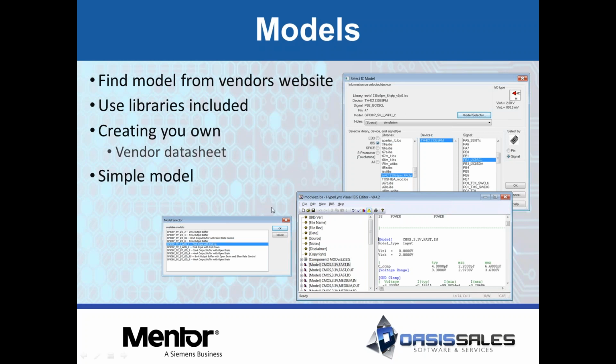There are multiple ways to get this information. You can find models very readily now on vendors' websites. Just about every IC manufacturer's website will provide IBIS models nowadays, just because they know their devices are switching faster than they were 5-10 years ago. The tool that you're using may come with a large library, like HyperLynx comes with a fairly substantial library of standard logic parts that you can choose from. You can create your own models from a data sheet.